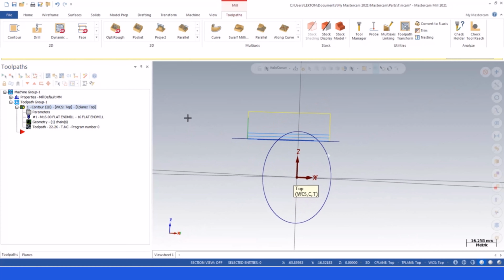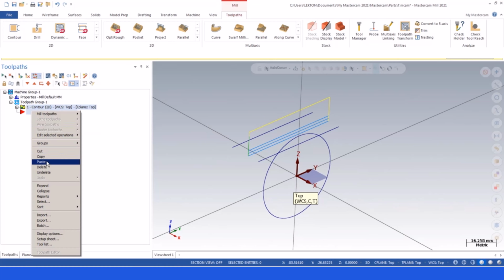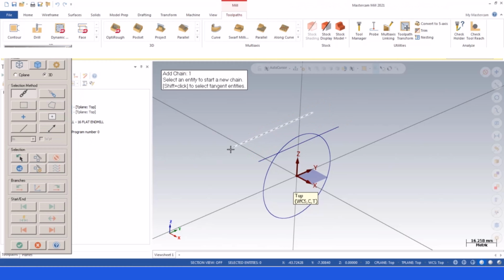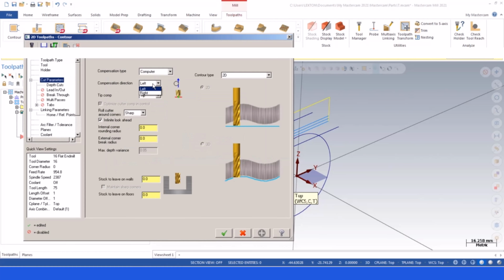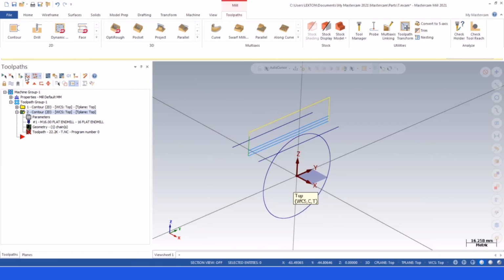Okay, this is going to be my toolpath, and then I can copy here and paste it here, and then click the geometry and select new one. That's going to be my new geometry. Okay, waiting for MasterCAM to respond at that point, and then we can click here, cut parameters, and we're going to turn left to right because this is my cutting direction. My tool is going to be on the right side, so we can recalculate it. Okay, everything seems fine.